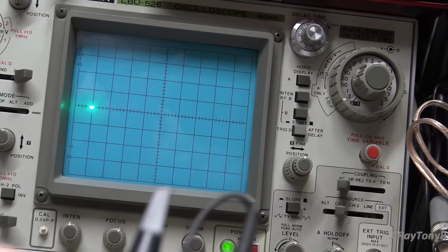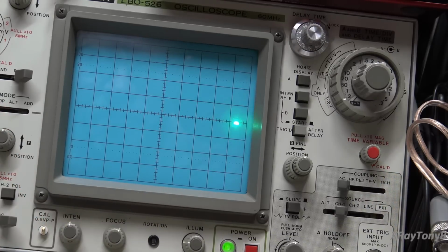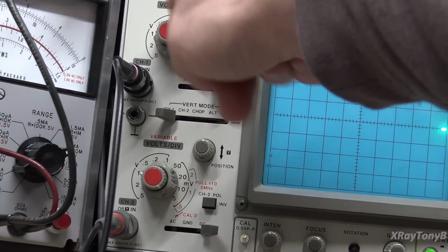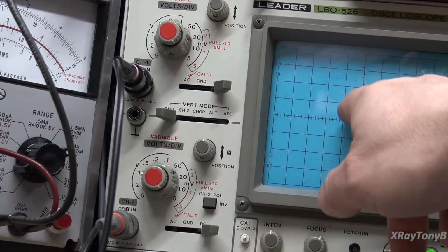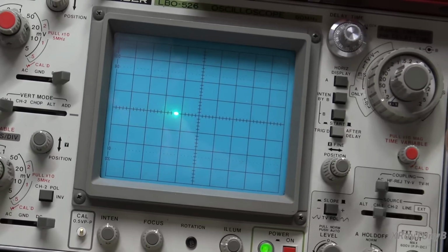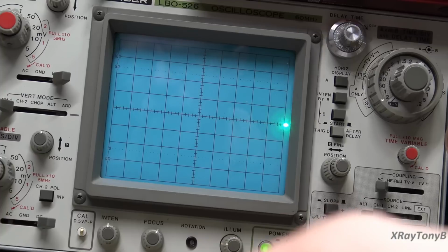But if I take my battery and I connect it to the probe, okay, let me pop the cover off the probe. See what happens? It goes up to about 9 volts. Now, how do I know that's 9 volts? Well, it has to do with how you set these knobs. You could set how many volts each little square represents. Go back and watch. I did a series on oscilloscopes. Go back and watch that, and it'll explain some of this to you. But this is just a quick review.